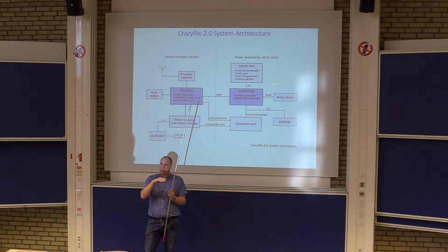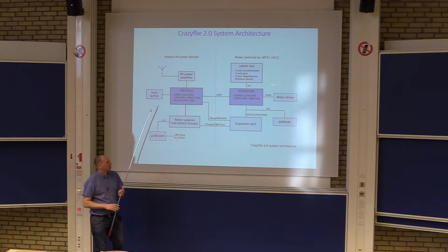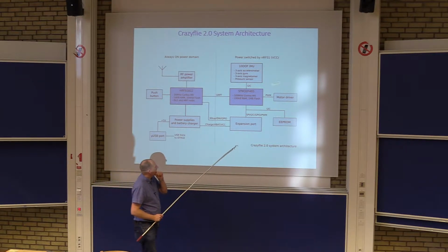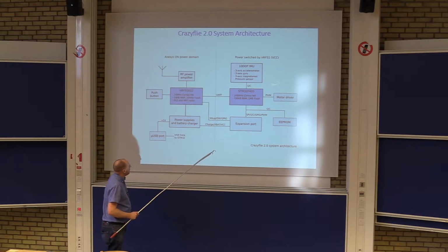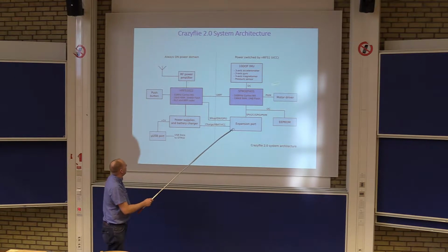So you do not control the voltage directly. Instead, you have a fixed voltage, and you just decide what percentage of the time the motors will get the fixed voltage. But in effect, that would be the same thing as controlling the voltage.